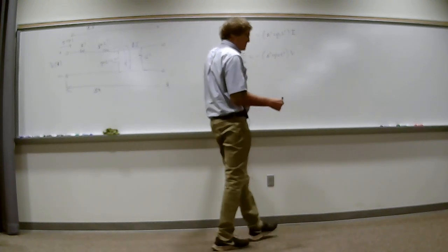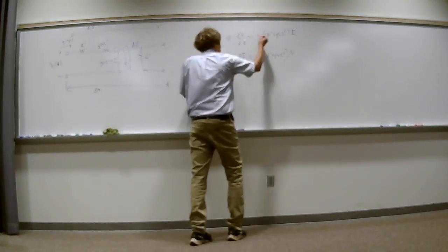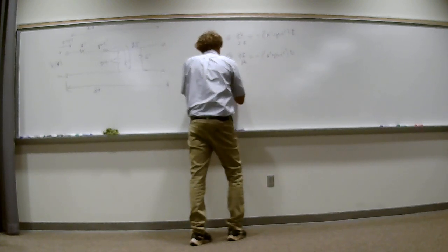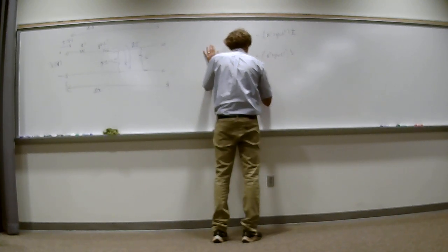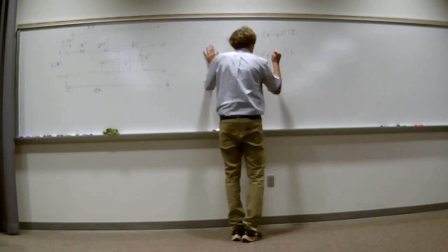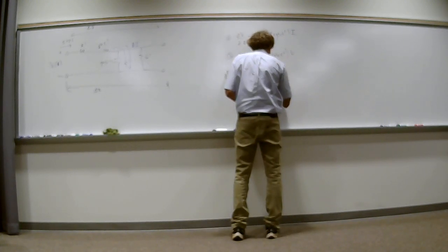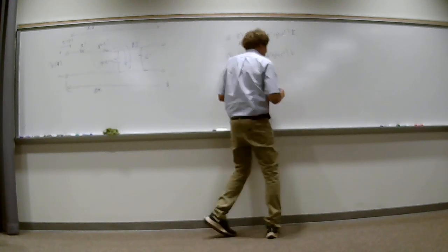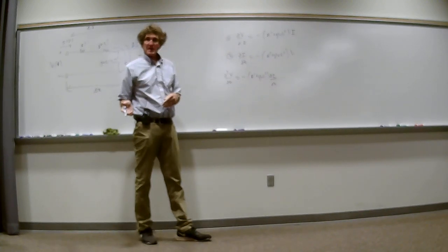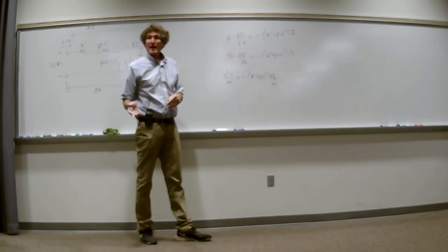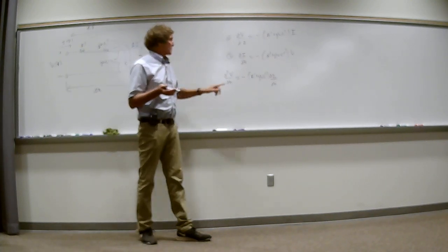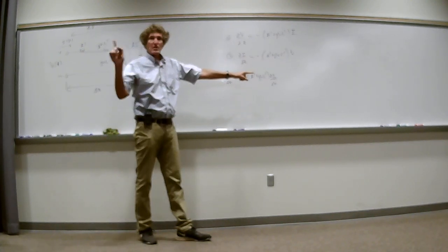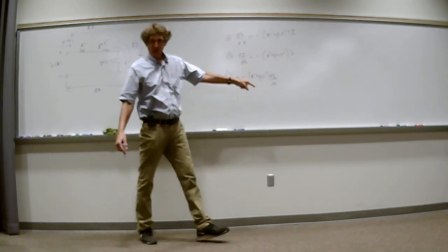For the voltage equation, when you take these two things, you take a double derivative, the second derivative of V with respect to Z squared, and now I get minus R prime plus J omega L prime, and then it's times dI/dZ, right? You all remember that? What did I do with dI/dZ, anyway? Say again? Plug in. Plug in what? You're right. Equation 2. I took equation 2 and I just replaced that, so I get one equation with one unknown. Y'all follow me, class? And I'll put that up here.